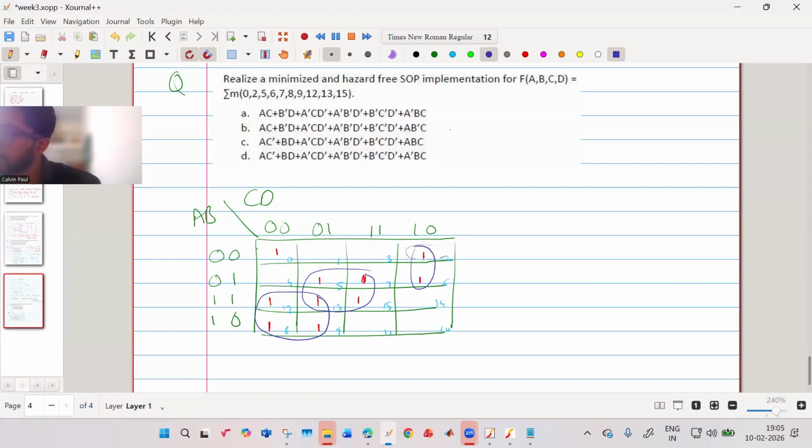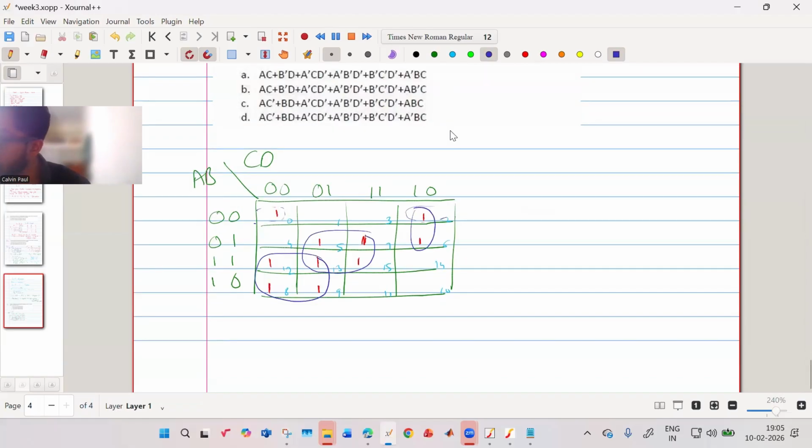And this is another K map we got. Okay. So let us write what is the output Y. So for the first four circle K map, it is given by A and C bar. Okay, I should have used different colors to be better that way.